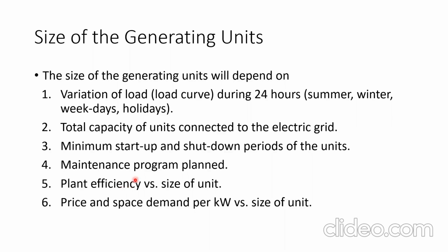Okay, but a load capacity that is much greater will give less efficiency. Means what? Overrated units will not be there. Similarly, underrated units must not be there, because if a unit is providing a power equal to 0.9 megawatt, and the load demand is 1 megawatt, then what will happen? The losses will be there. Okay, heating losses will be there. So underrated or overrated units will not be there. You have to select the exact size of a unit.